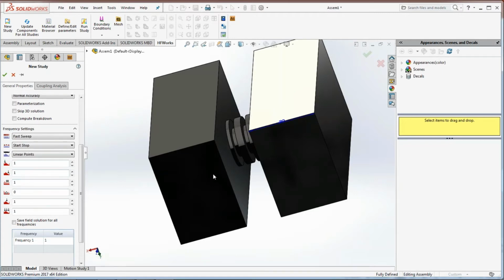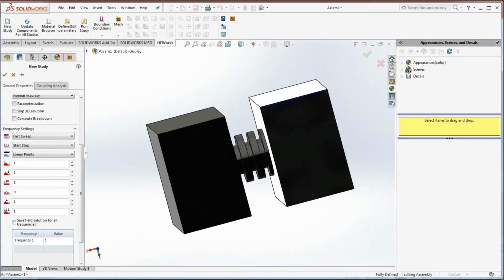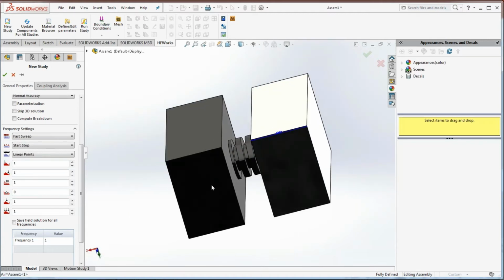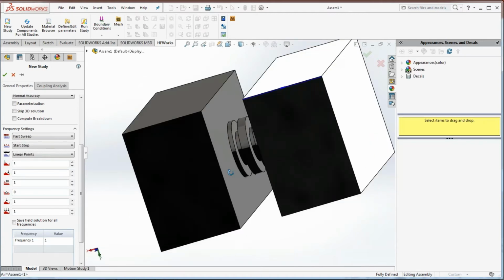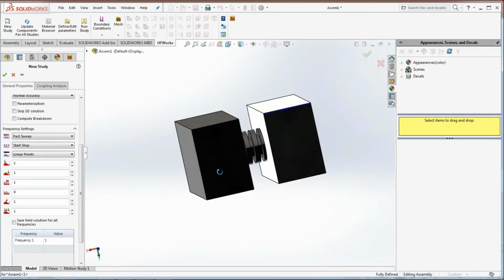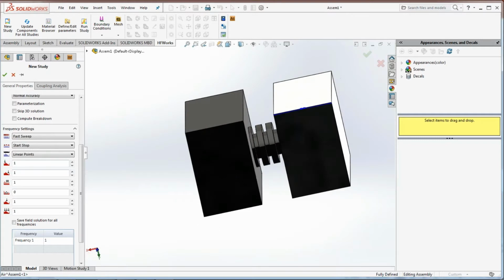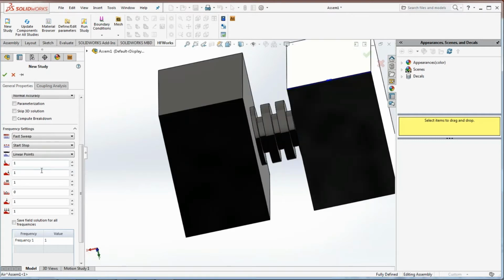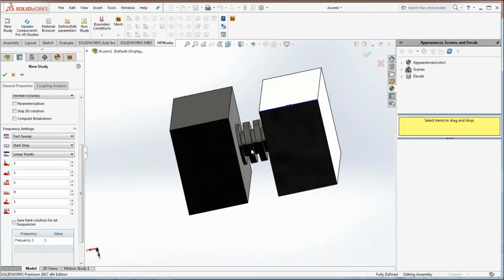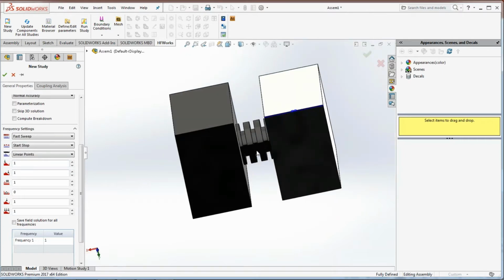So for example, in this one, my concern is the 2.45 gigahertz, where the home microwaves work, and like many industrial microwaves, the ones that use 2.45 gigahertz magnetrons, of course. So let's say I want to monitor the effectiveness of this filter between 1 gigahertz and 5 gigahertz.